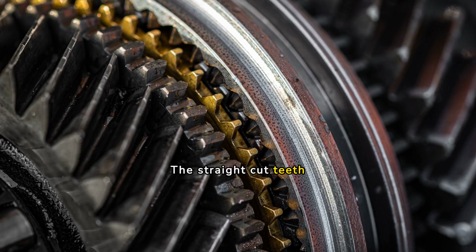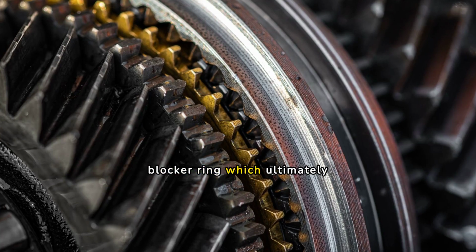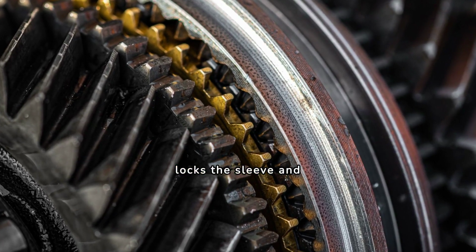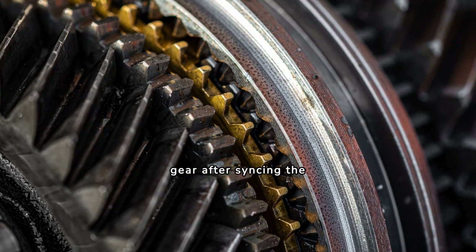The straight cut teeth present in it are used to lock on to the synchronizer blocker ring, which ultimately locks the sleeve and allows it to rotate at the same speed as the gear after syncing the speed.